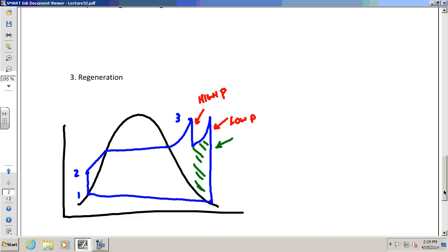But that's a visualization there. I wanted you to visualize that you'll have multiple turbines that help add area in the TS. Let me label this. This is a TS again, temperature, entropy. This is the graph associated with number 1. It's the same graph, except now I've added this extra turbine. That's all. Okay?